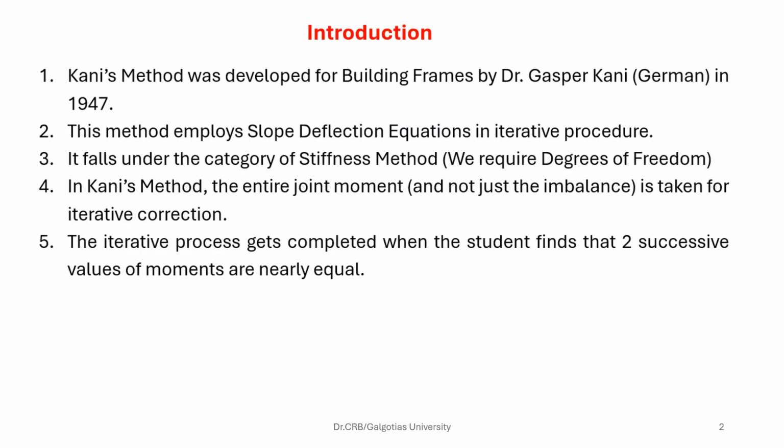Now here we go. Kani's method was developed for building frames by Dr. Gasper Kani, a German, in 1947. This method employs slope deflection equations in an iterative procedure. It falls under the category of stiffness method. We require the degrees of freedom.